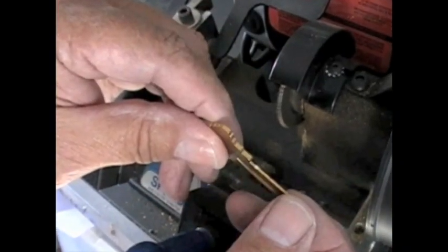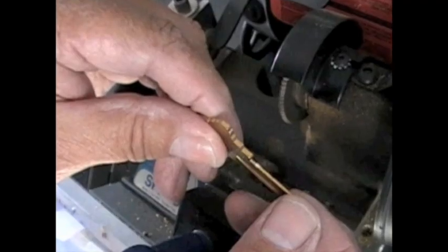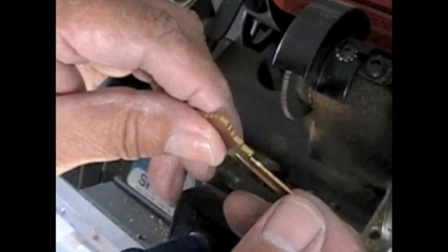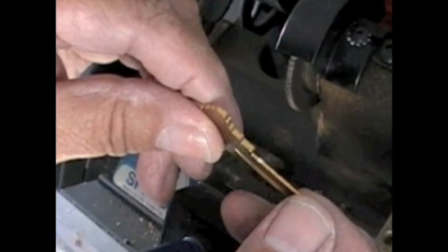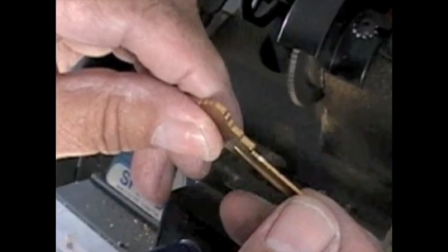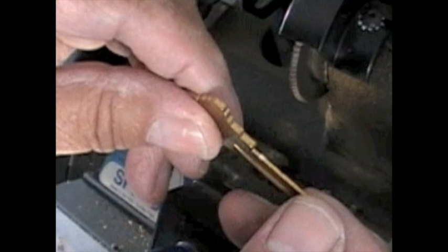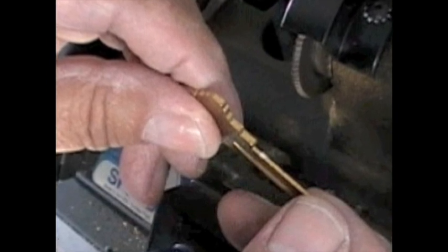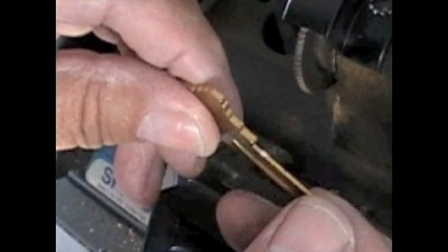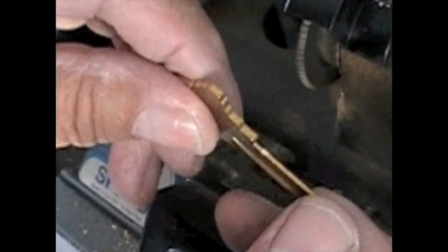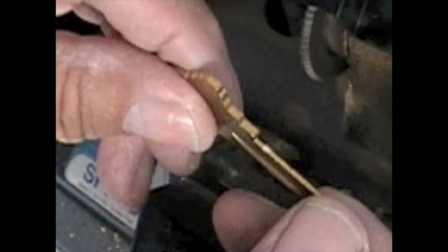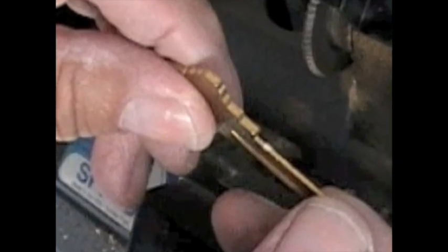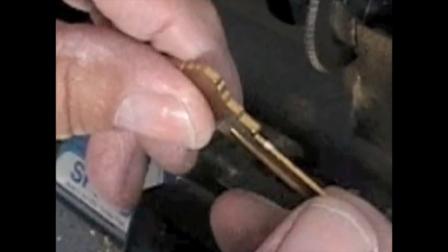It's going to be hard to see this on the video, but what I actually like to see is just a tiny cut on just one corner of the key blank. And if it just starts to cut the key, by making just a small cut on one corner, then I know the machine is set properly. Now, of course, as I mentioned, you should also check the manual for your key machine and see what the manufacturer advises as far as adjusting your key machine.